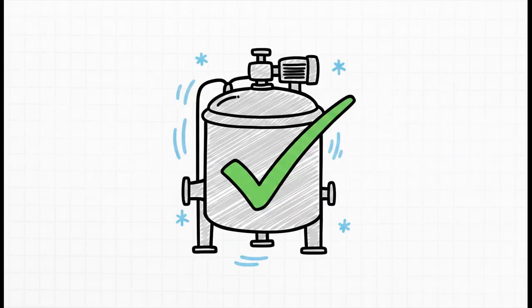If you're training new staff or maybe simplifying your shop floor documents, this is the real-life, simple understanding you need to hammer home. The machine is working properly. That is qualification in a nutshell. If you're checking whether a mixing tank operates as per its mechanical requirements, you are qualifying it. It is strictly about the machine itself.